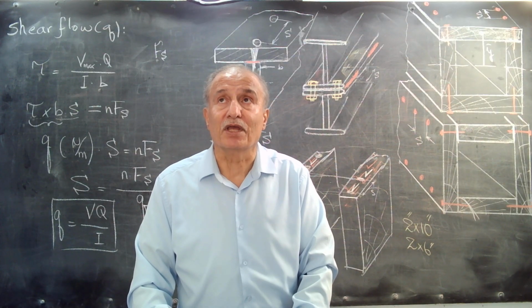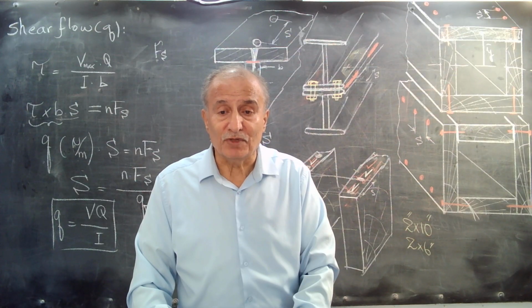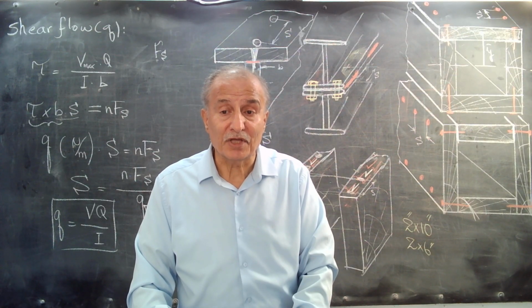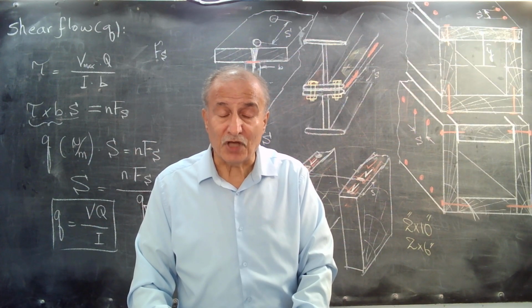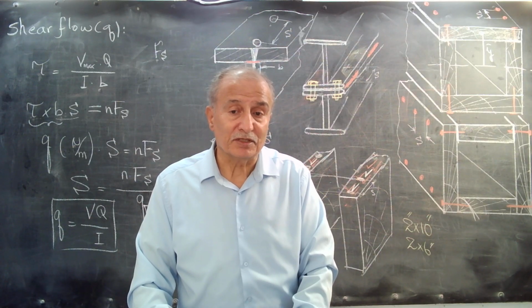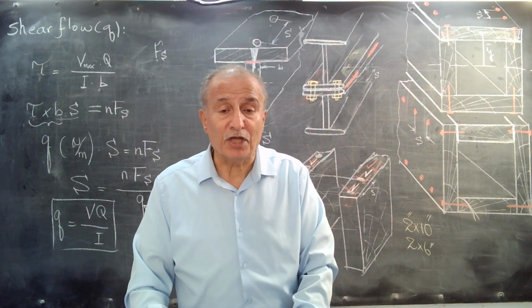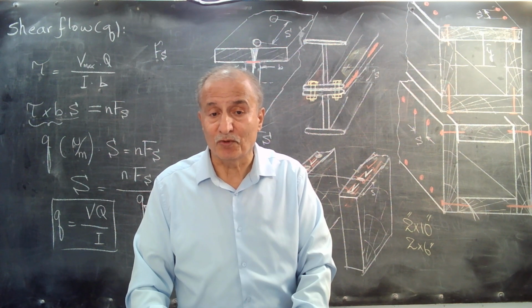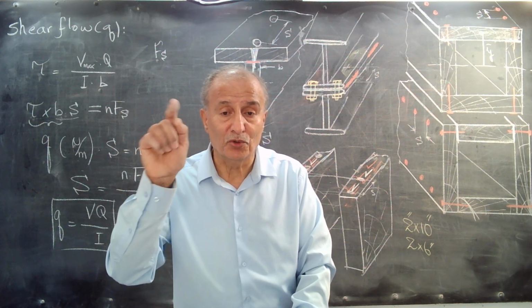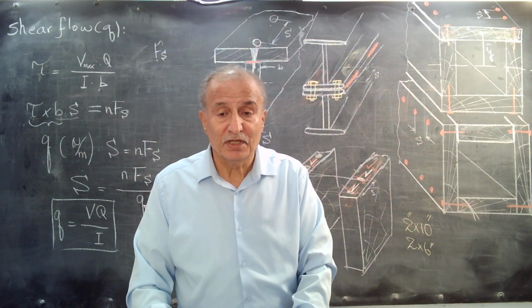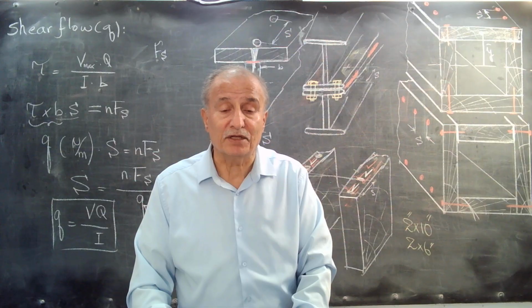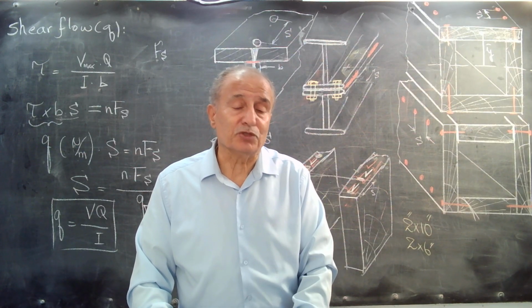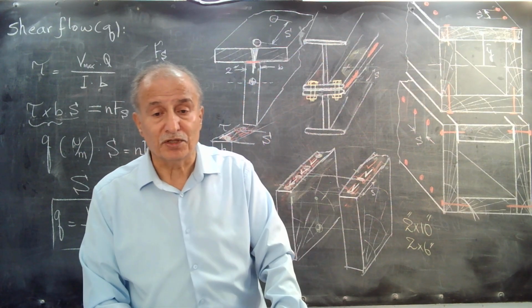In the building, if you look at the joists, you will see some of them close to the support have a crack or a split. And a notch is another cause of failure. The size of the notch, the holes that they make for pipes or electric power wires to pass through the joists, must keep a minimum distance from the edges, and the size is also very important. Many things must be considered in a wooden beam.